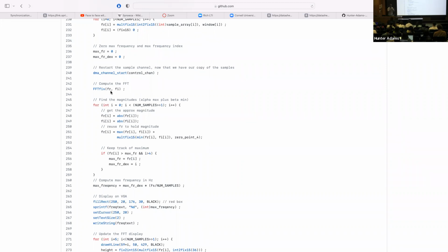Is it in the long pause between chirps? Is it in the chirp synthesis state? Is it in a syllable producing state, right? So you ask which state are you in, and the other piece of information you ask is how much longer are you going to be in that state? Because like I mentioned last time, it takes a long time relative to the other processes going on here, it takes a long time to fill up that ADC buffer.